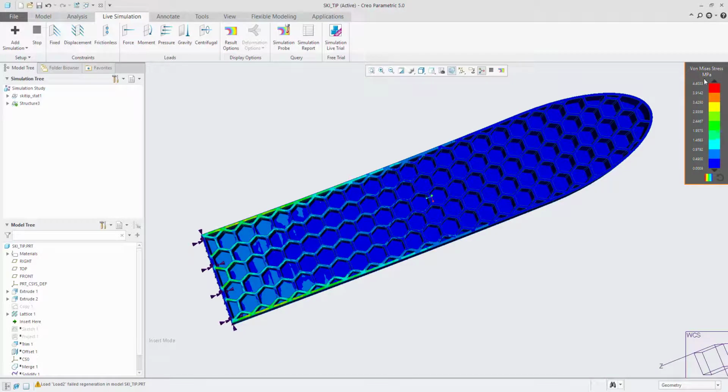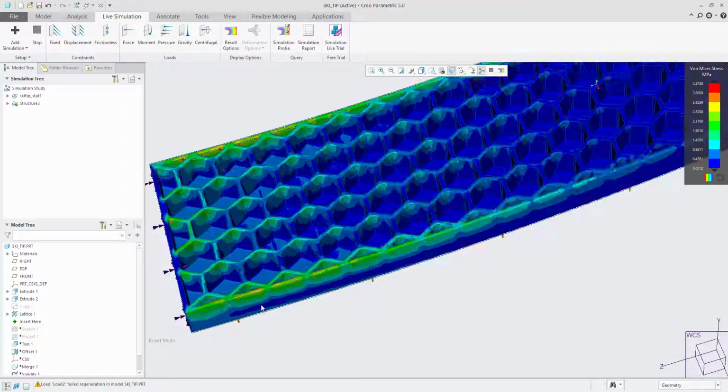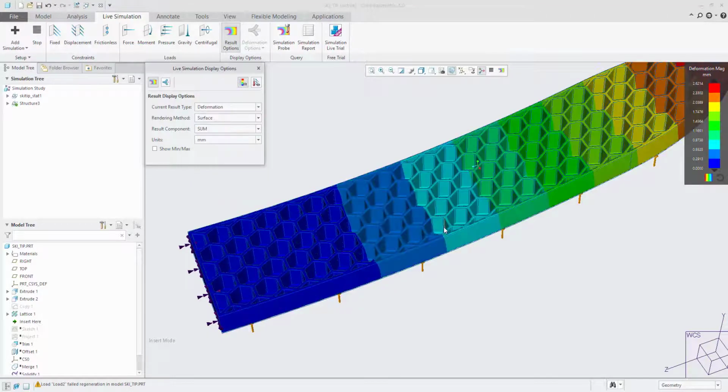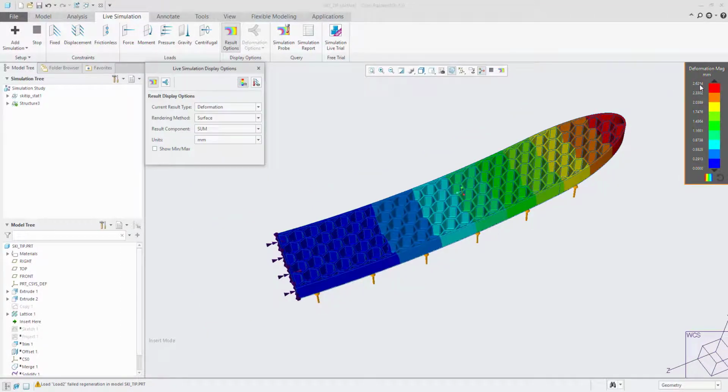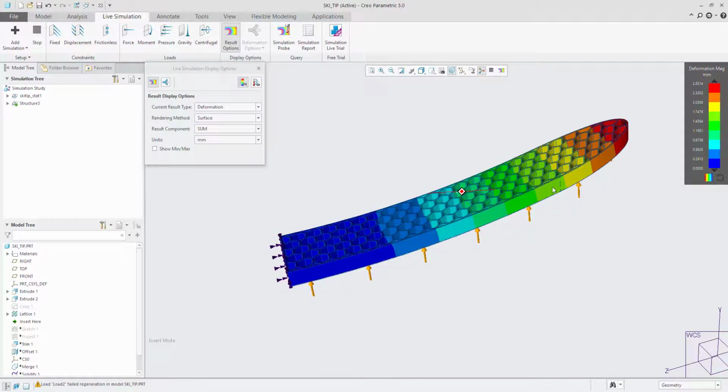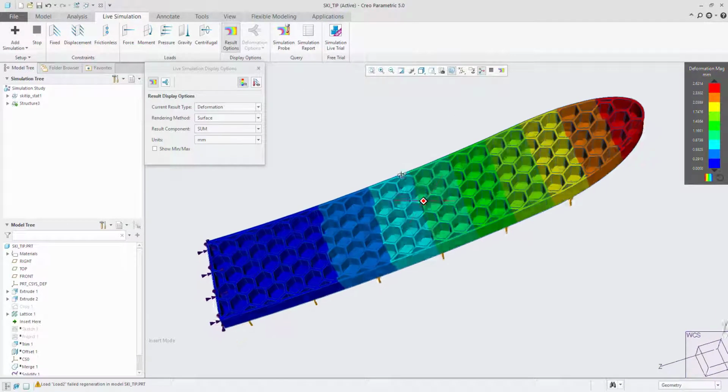So now I can see here, we've increased the stresses a little bit, but not too much. But we might want to look at the displacements again. The displacement now has gone to 2.6 millimeters. So we've made it, like some percentage, 30-40% less stiff. But as a designer now, we can play these games about, well, what can we change? What if we change that? Why don't we change something else?